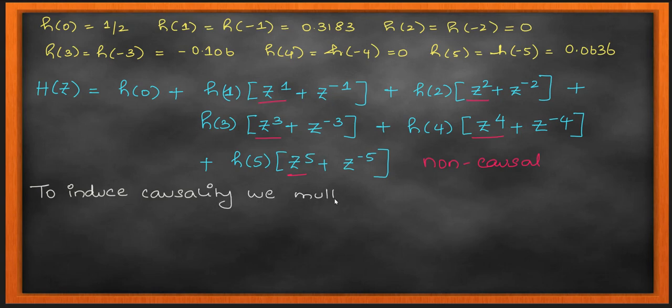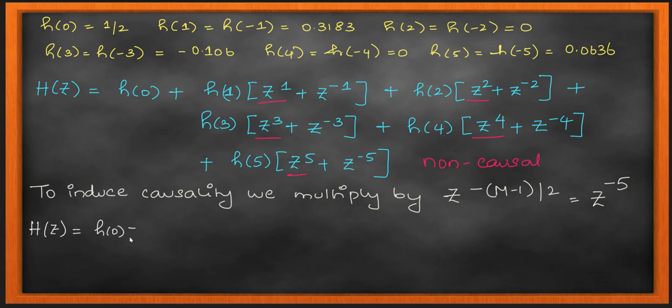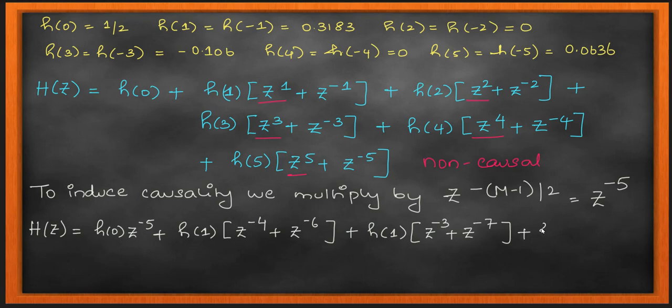So we are going to see different design techniques, and we are going to do different numericals for each design. But in every design, you will see that this non-causal to causal conversion is the same, and it exists in every FIR design numerical. Irrespective of the design that you are adopting for your FIR filters, this symmetry across the origin has to be removed, right? That is what it means. So I'm turning from non-causal to causal by shifting it from -5 to +5 to 0 to 10.